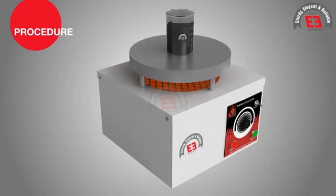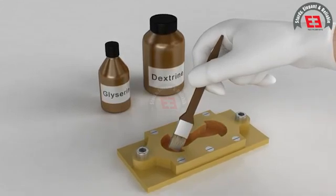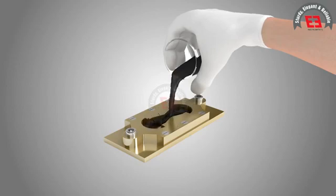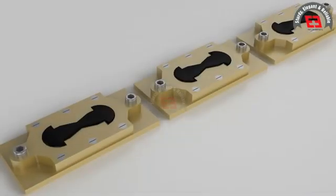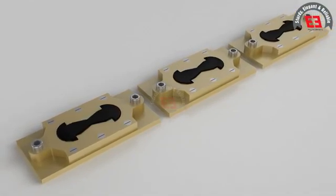Procedure. The bitumen sample is heated to a temperature of 75 to 100 degrees Celsius above the approximate softening point until it is fluid. The solution of glycerine and dextrine is applied on all surfaces of the ductility mold where bitumen is exposed. Now, bitumen is poured into the ductility mold assembly until it is more than level full. A total of 3 specimens of such type are prepared to conduct the test simultaneously.